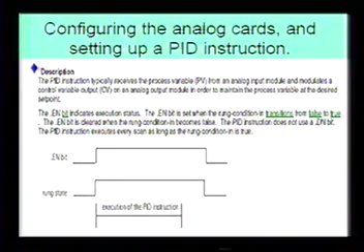And then the control variable uses one output as a minimum. And if you'd like to know what the valve's position is, like position feedback, you would have another input. So you'd use 2 of your 8 available.